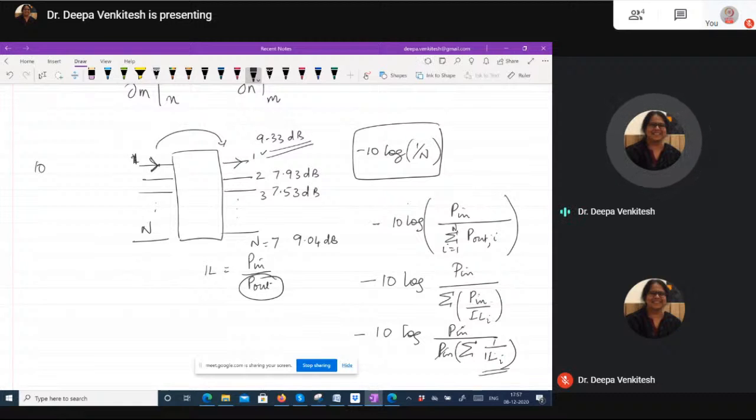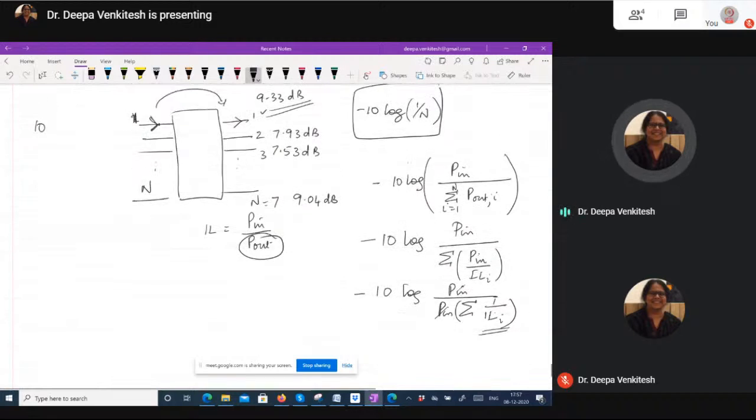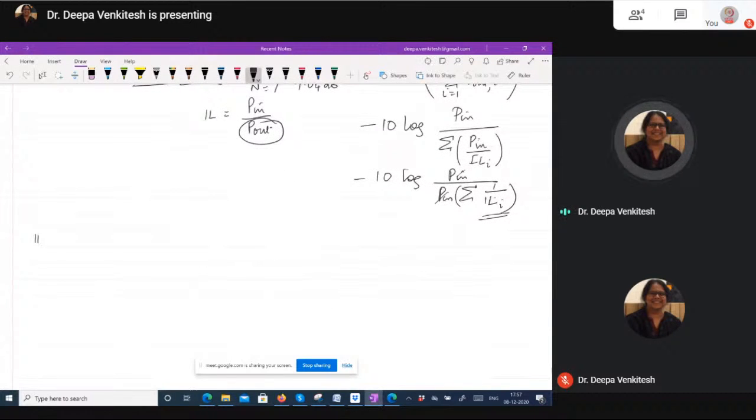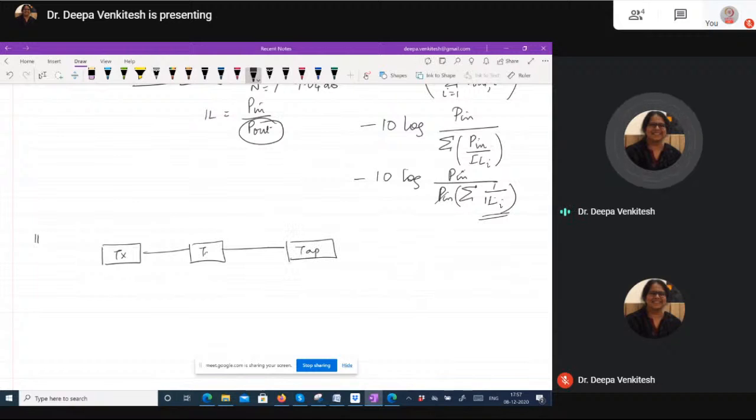And the last question is, a cable TV operator uses an optical bus. There is a transmitter, and then there is a tap coupler. Tap coupler means a coupler where the split ratio is such that what you're taking out is much smaller than what is in the feed through path. So this is user 1. You can think of what topology this is.